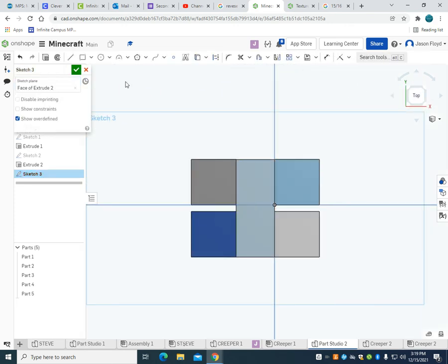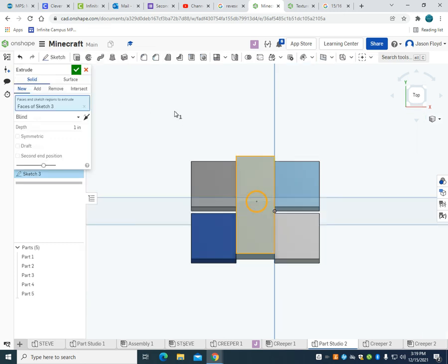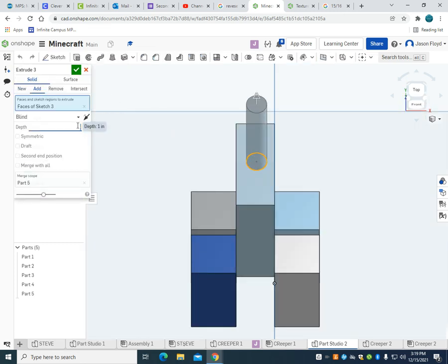The next thing I'm going to do is make that top here. Now, depending on which kind of joint I'm going to do, this is either going to be a cut or an extrusion. So on the first one, I'm going to do it as an extrusion. I'm going to go 0.2 on this one, and I'm going to make sure that it is centered. To make sure that it's centered, it's going to be 0.175. And I'm going to extrude that 0.2 inches.